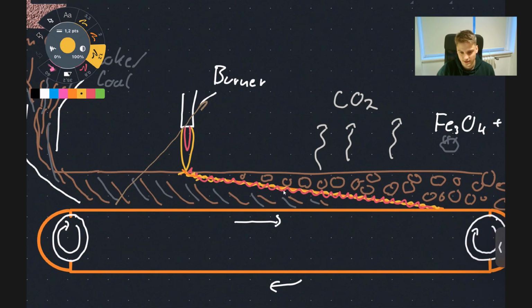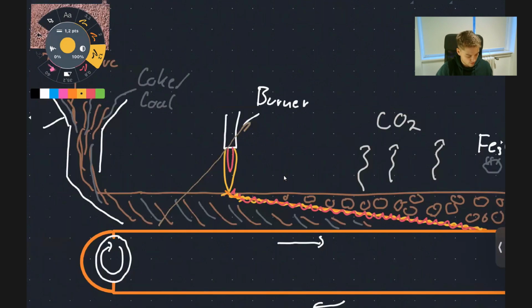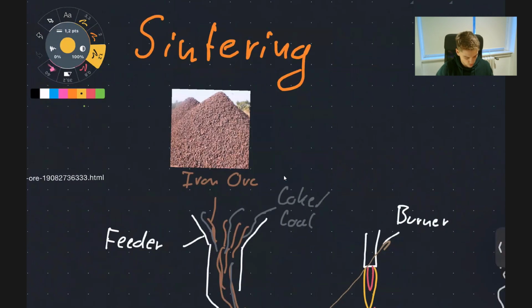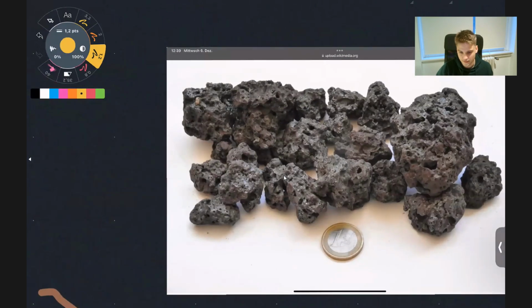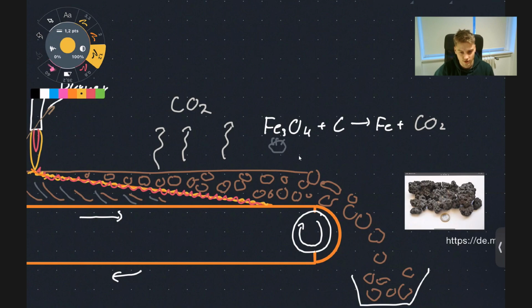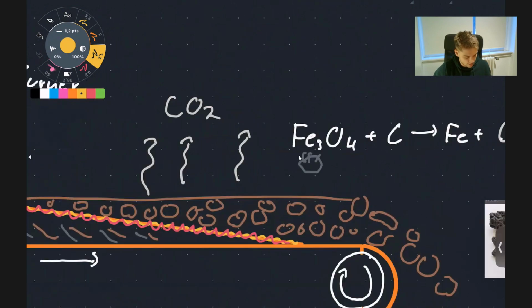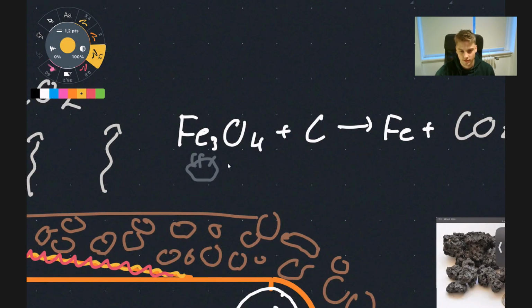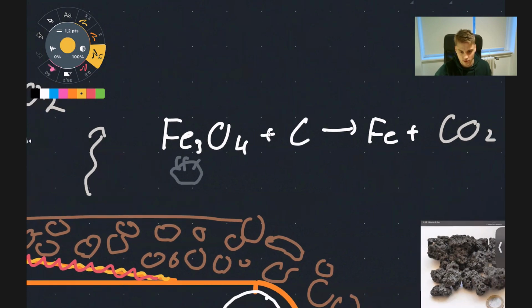The reason for that is that if we burn the coal and iron mixture, the iron ore can clump together, can fuse together to get from a form like this to a form like this, which is better suited for the blast furnace application. Another advantage is that the iron ore is already partly reduced. Iron ore is typically found in iron oxides, so iron and oxygen, and we only want the iron, so we have to get rid of the oxygen.